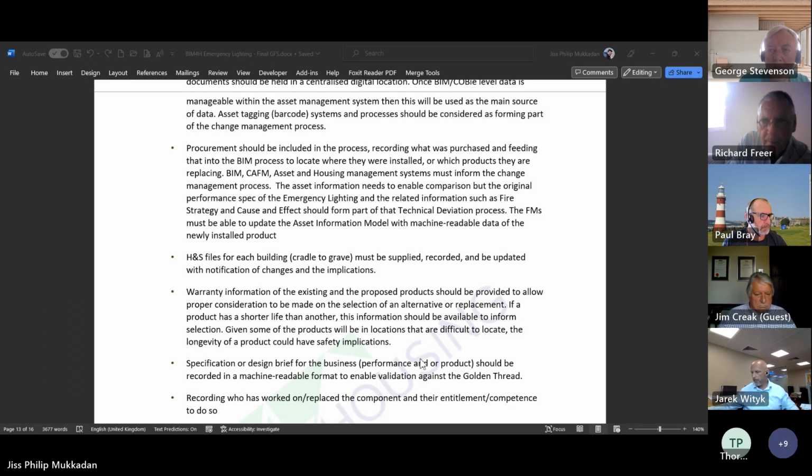No, the discussion for me, for my role, is a little bit highbrow. All I need to know, in my role as a fire risk assessor, is: is it in place? Is it suitable? Does it illuminate the means of escape? And is it tested daily, monthly, annually and five-yearly?